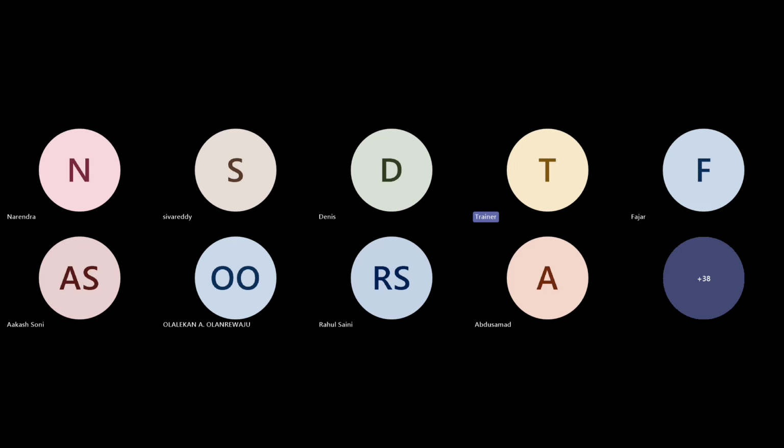We do not do separator sizing to separate H plus ions and O minus ions; we generally use other methodologies to keep that concentration low. Yes, we do separator sizing for the water, which is carried out along with the hydrogen ions across the electrolyzer membranes.